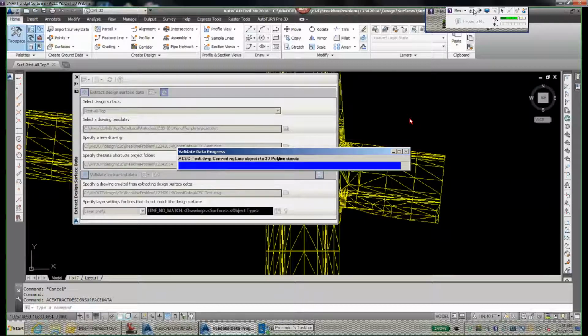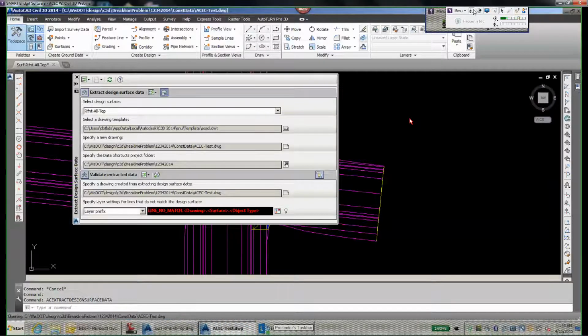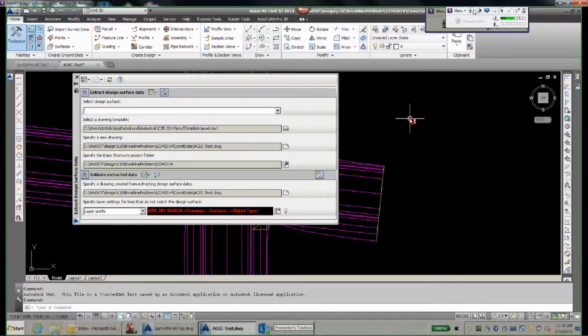So if you think about the order of operations for building a 3D or a refinement surface, first you paste in your datum, your refinement datum surface, which is made from the corridor datum surface. Then you paste in the corridor top surface. So everything that came from the corridor top surface is going to nullify any break line that came from the refinement datum surface that was inside that footprint. It's going to trim and delete any of those lines automatically for you.